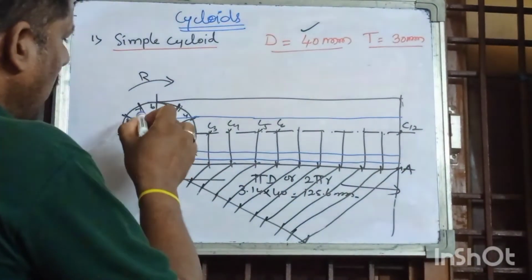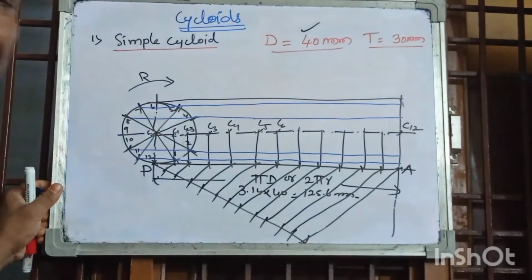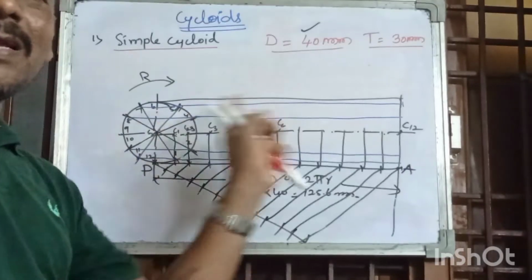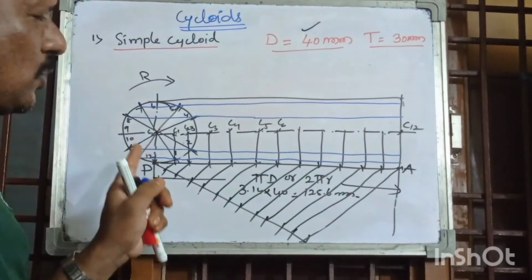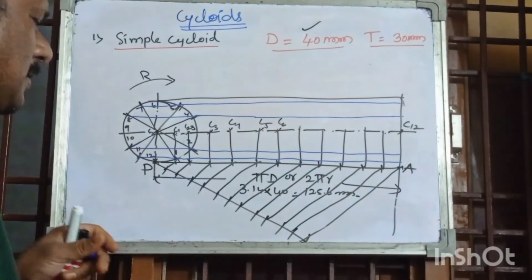Draw the line. And next is 7 and 5. These two points coincide. Draw the line. So whatever the circumference points are there, just project them horizontally, and all those lines should be parallel, horizontal parallel lines. Okay, parallel lines.